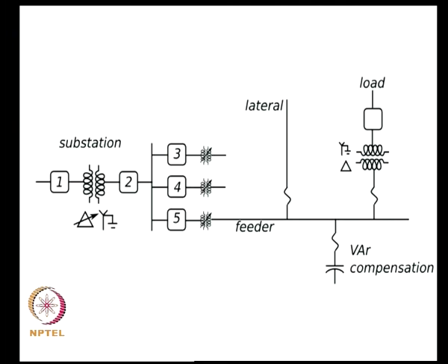Before the substation, you have the transmission system, the sub-transmission system, etc. So, what comes into the substation is the high voltage aspects, and then you would have the transformers at the substation, followed by the low voltage bus, and then you would have feeders going out from your substation to your actual consumption points.